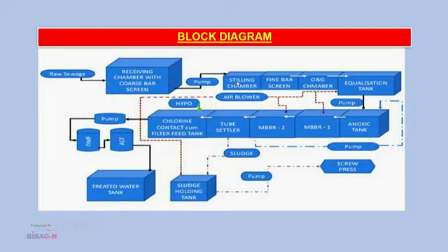Stage 5 is fine screening. Sewage is screened through a bar screen in order to remove fine floating material and solid particles. Stage 6 is oil and grease removal. The oil and grease present in sewage is to be removed before it enters the process, as it makes a layer on the MBBR media which restricts the development of bacteria.